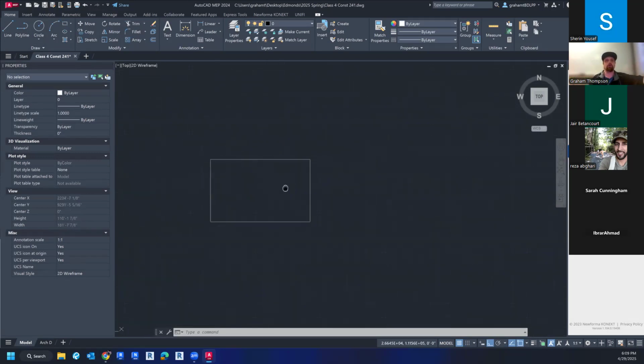So once again, I'll do this one more time real quick. Okay, line tool. I'm just going to draw one next to it. I'll delete it in a second, but I'm going to click here. I'm going to draw a line, move my mouse to the right. Again, I've got my ortho mode on, so I know I'm drawing straight.